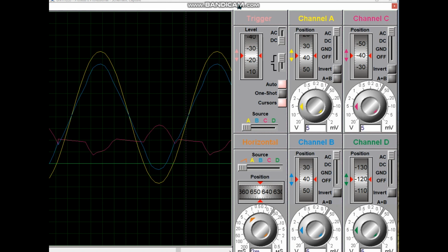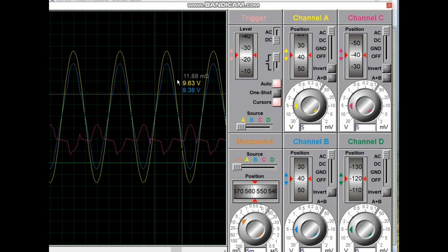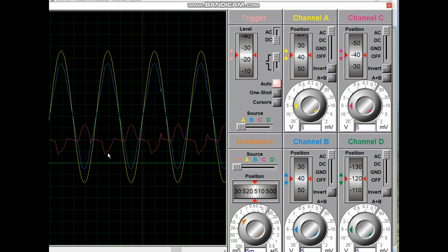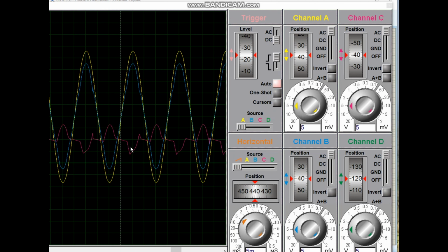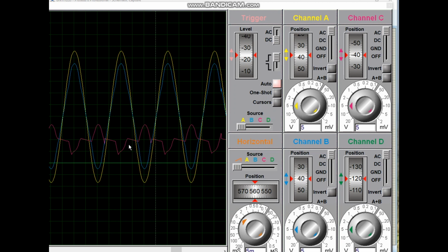And we click debug and oscilloscope. We see the oscilloscope output and how it rectifies. It is not a fully rectified signal because the capacitor value is small, so we cannot rectify fully. Only some portion is rectified. We see the DC is not fully DC current, but a portion of it is DC. If we increase the capacitor value, we see the DC is more accurate.